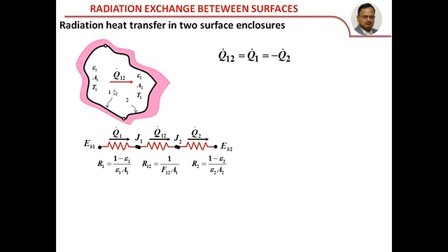And then the energy has to flow, and only some of it will fall on 2. So you have in between the shape resistance. Because of the emissive nature of the second surface, its emissivity is not equal to 1, only a fraction of it will be absorbed. Hence, this also offers some amount of surface resistance called R2.